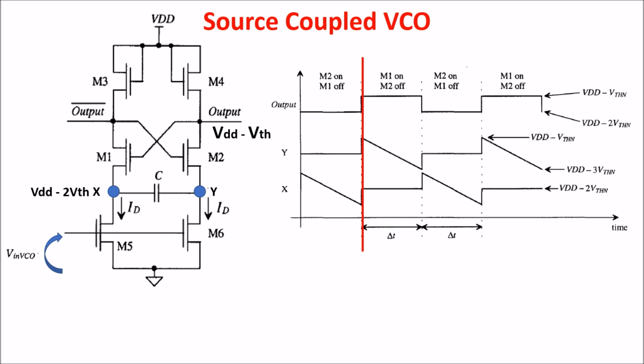So you need to size carefully all the MOSFETs and define the V threshold carefully. M1 and M2 used as switches need a low on resistance, so they should be larger in comparison to M3 and M4. Moreover, the oscillation range is just 1 V threshold, so you need an inverter on the output to restore the logical values.